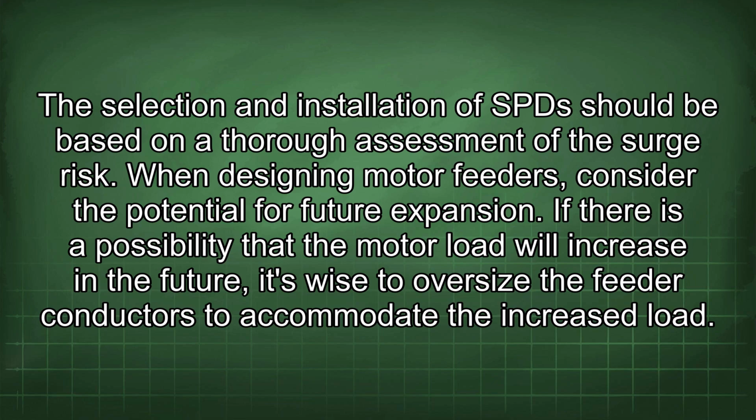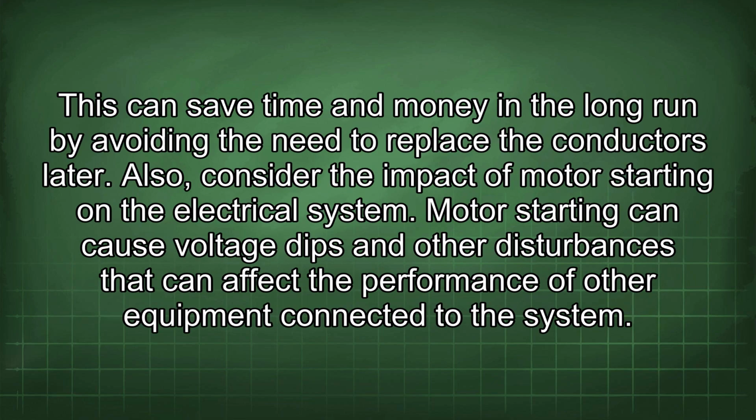When designing motor feeders, consider the potential for future expansion. If there is a possibility that the motor load will increase in the future, it's wise to oversize the feeder conductors to accommodate the increased load. This can save time and money in the long run by avoiding the need to replace the conductors later.